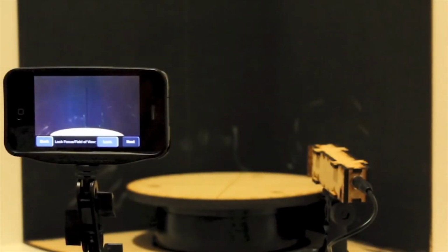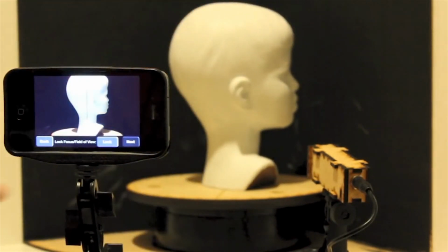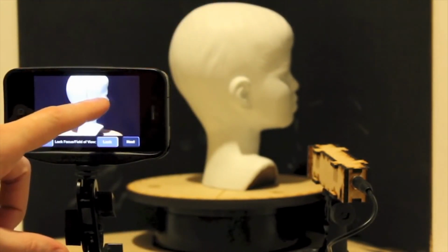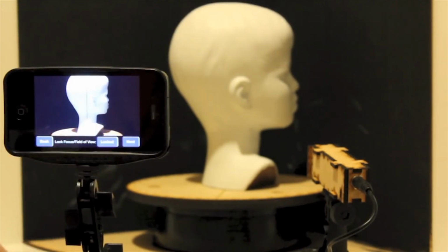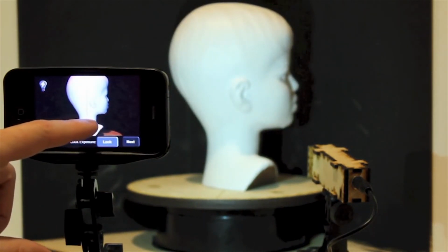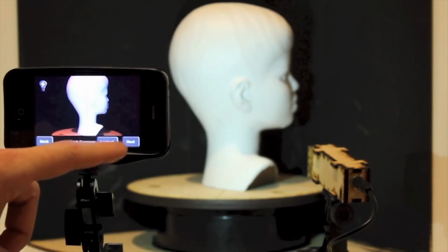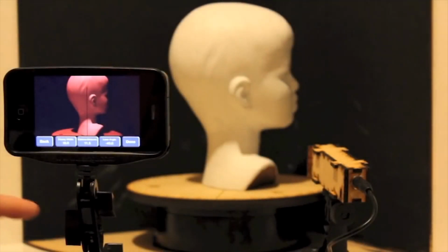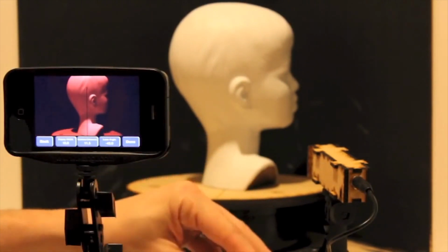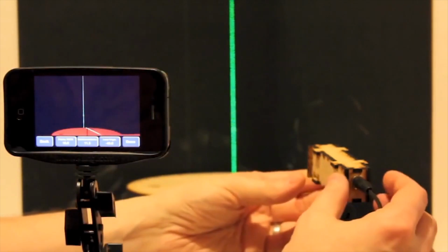Non-contact devices use lasers, optics, and charge-coupled device (CCD) sensors to capture point data. Although these devices capture large amounts of data in a relatively short space of time, there are a number of issues related to this scanning technology. The typical tolerance of non-contact scanning is within plus or minus 0.025 to 0.2 mm. Some non-contact systems have problems generating data describing surfaces which are parallel to the axis of the laser.